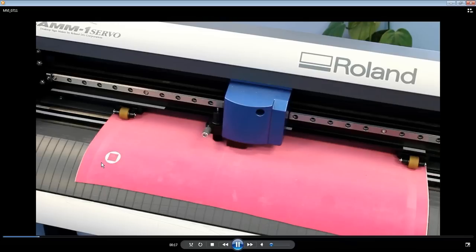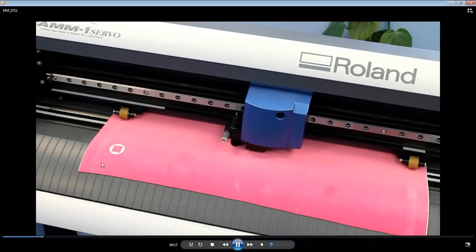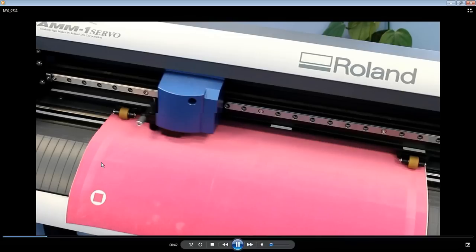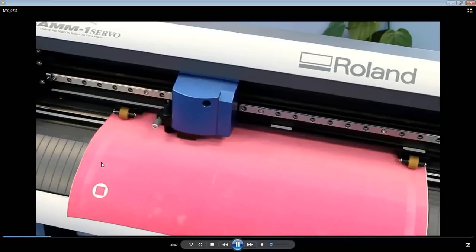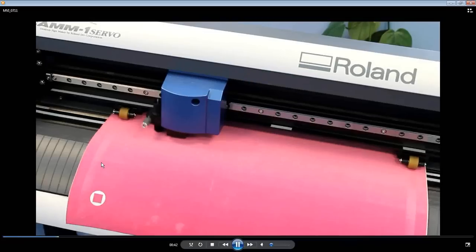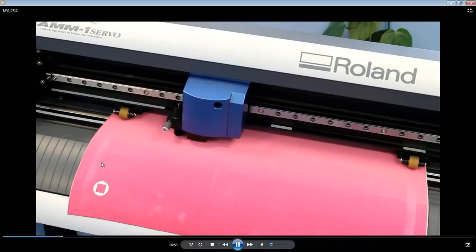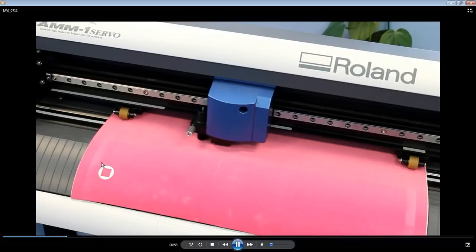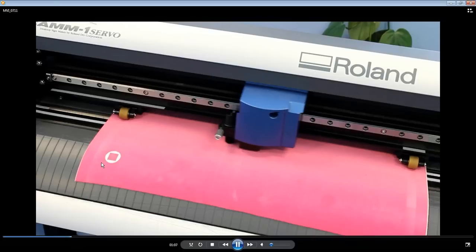Also, you need to change the offset. The offset is the measure of the tip, the distance between the tip of the blade and the center of the blade spindle as it spins around. So there's a little bit of a distance between where the design actually sees the center of the line that it's cutting and where the tip of the blade is actually at. So normally for a 45-degree blade, our offset is about a 0.250, and on a 60-degree blade, it's going to be 0.50. So it's very important to change that so you get complete cuts on this.